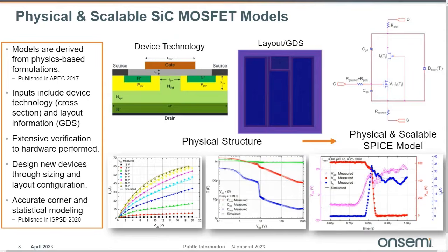on those parameters. You can see on the bottom of the slide the on-region curve, where the slope of the curve changes when the current increases. It's due to the fact that if the current increases, it generates more losses inside the MOSFET, and so we have more temperature increase, and so less capability, because the RDS(on) increases, less capability of conducting current.